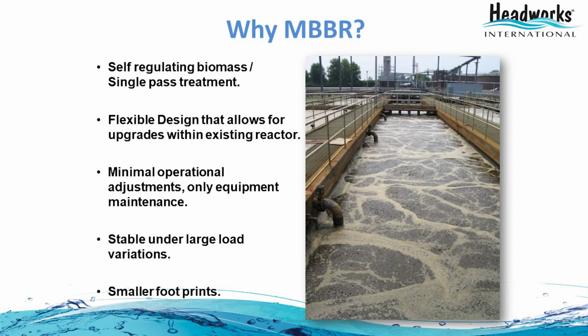You can upgrade existing systems and retrofit existing tanks. If we are doing only BOD removal, for example, within the same tank we can add on nitrification, denitrification, as well as phosphorus removal. In a pure MBBR process, you don't need any kind of operational adjustment for anything inside the tank. What I would need to do is outside the tank, like pumps and blowers, those kinds of things.